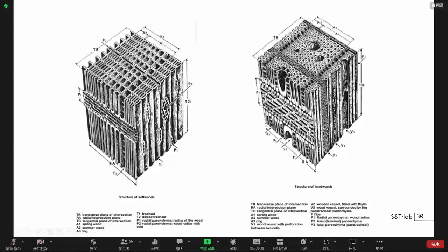What you can see also is that you have this kind of tubes, and these tubes explain that the behavior of timber will be quite different according to the direction you are looking at. If you put tension forces along these tubes, with no knots in the timber, it will be very resistant.